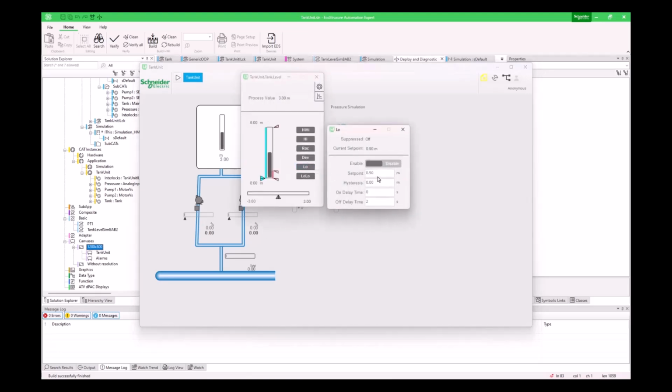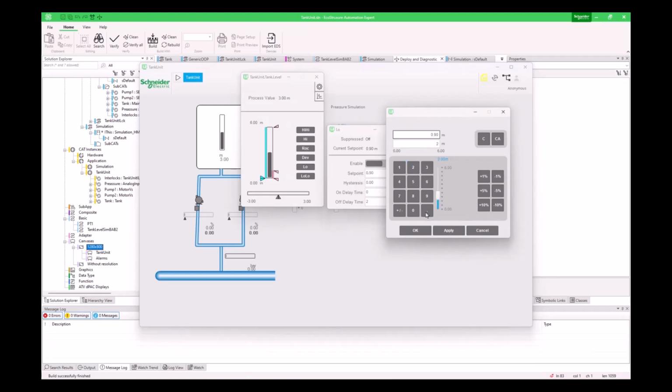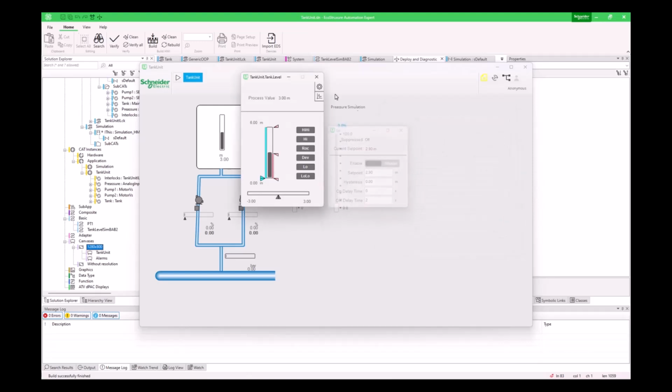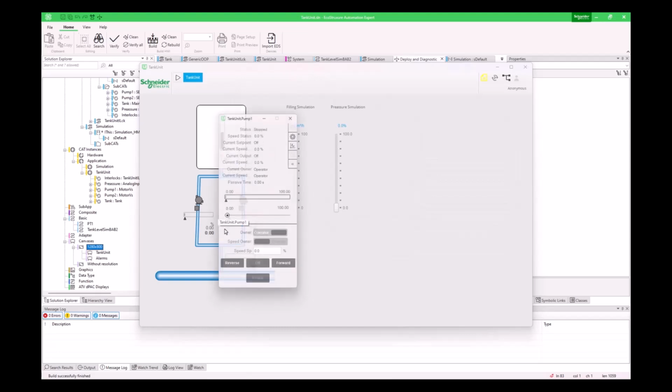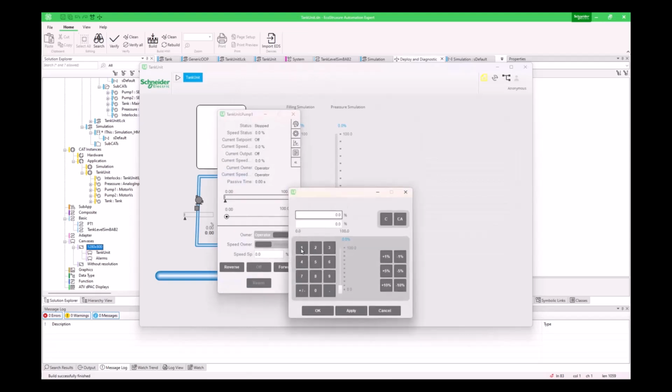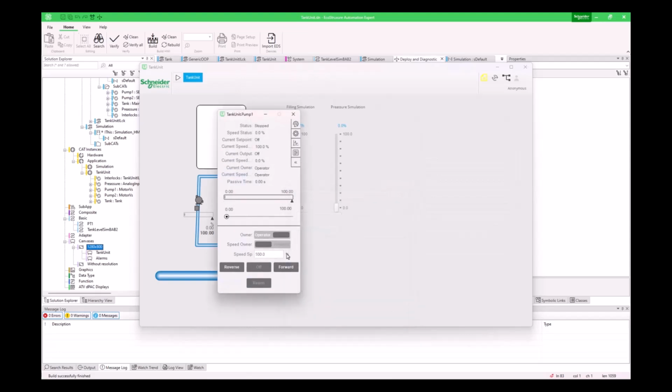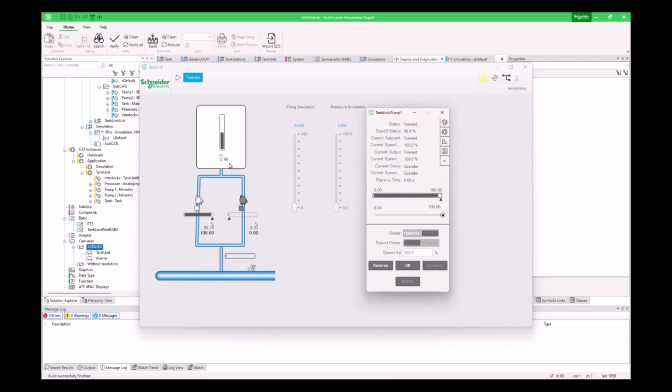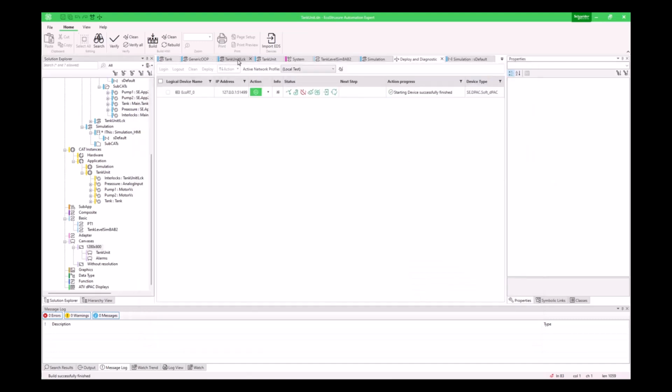Testing now, I set the low level to 2.9 meter and start the pumps. The interlock activates, but I made a mistake. It blocks the pump from turning off, not on.